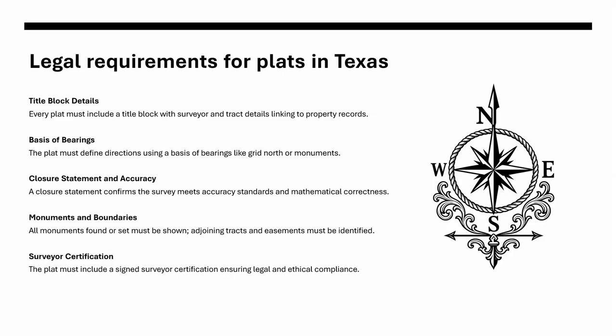Fourth, the plat must note every monument found or set. If the crew finds an iron rod, you must show it. If they set a new iron rod, you must show it. If they recover a stone mound, it must appear. Monuments are the backbone of our surveys. They are the physical evidence that ties the paper to the ground.